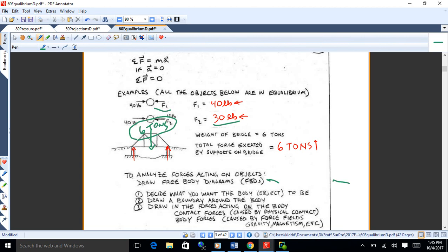So when you're taking these classes at the beginning, they tell you what the loads are, what the forces applied to the objects are. They just show it to you. What you're going to be working at is finding the reactions on the supports, and that's what we use statics for. We know what the loads are. We want to figure out what those red forces are on the footings that support the bridge there and there, okay? So that's what we use statics to do, to solve for those unknown support forces, and they're called reactions.